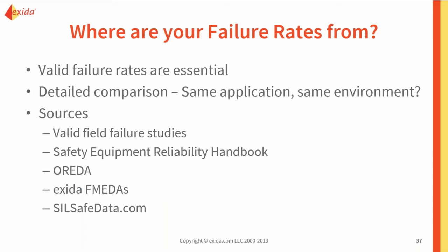So where do the failure rates come from? Well, first of all, you have to make sure each device has valid failure rates in a detailed comparison. Make sure it's the same application in the same environment. Don't compare a cabinet mounted, controlled climate, clean service valve with one that is going to be a mile below sea with severe service run through it. It's not an apples to apples comparison. Make sure you know where your failure rates are coming from.